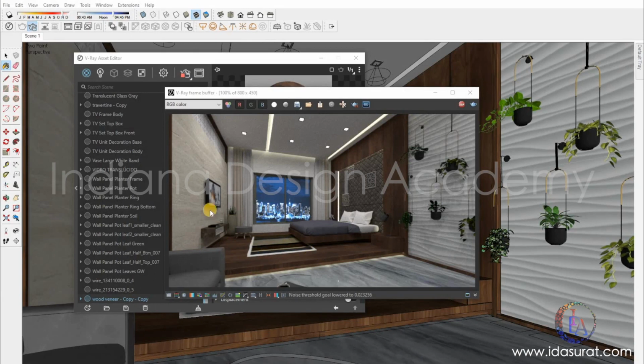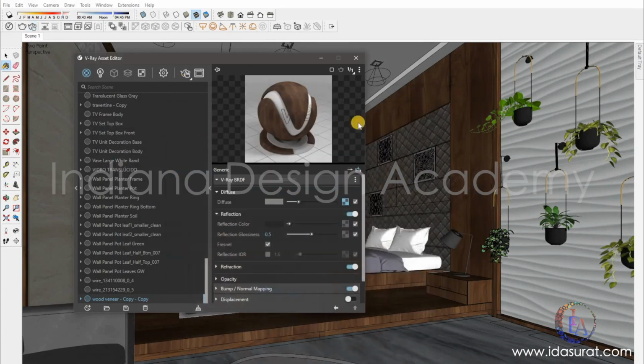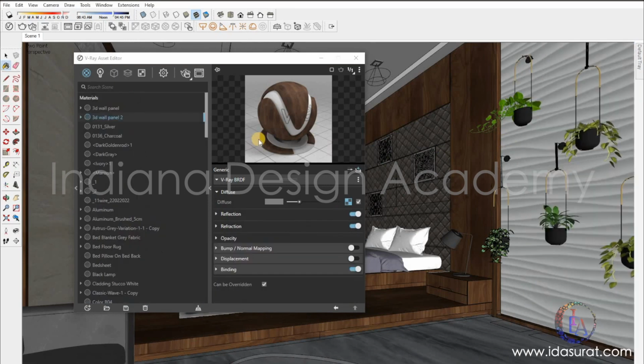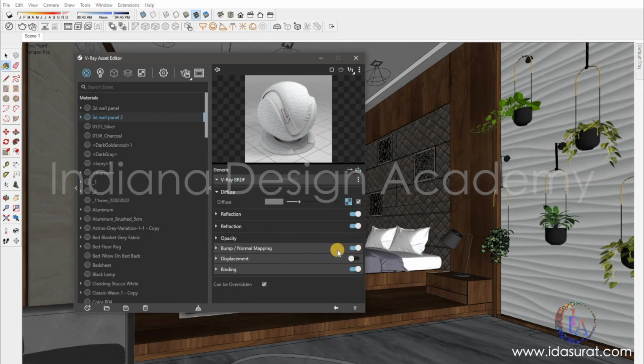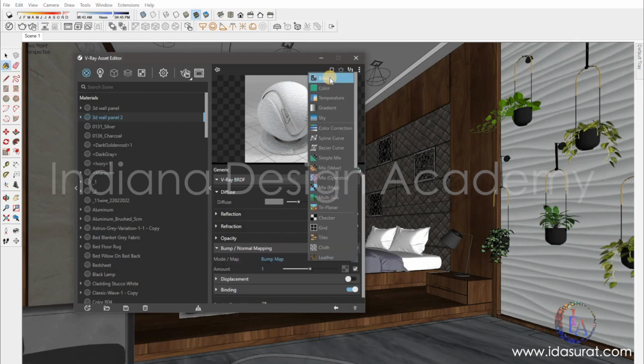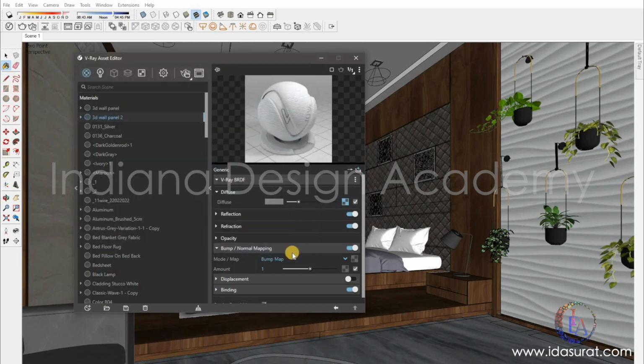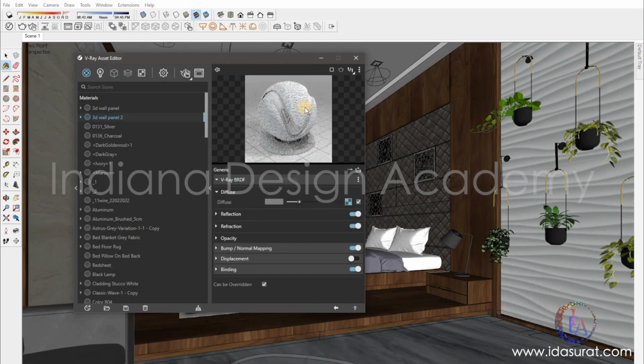Previously we have set this material. Now we'll be setting the travertine material and this 3D panel in this case. Okay, and the interactive render was on. Let me now set this. I use the dropper, click on this, so it shows me in V-Ray regarding this. At present I don't have any bump map and image placed, so I don't see any effect. Now I have placed this image, I have taken the same image from the folder. Previously what you saw, and now you see the effect.